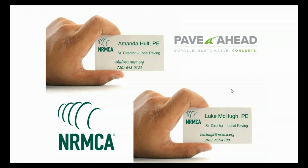So many times we might include an expansion joint in areas where we feel like there may be blowups. Sometimes when we get to toll facilities, we'll put lugs in there to keep movement of panels limited, particularly when we're using CRC pavements. So in those types of situations, sometimes we might include an expansion joint there just to accommodate a little bit of that movement, but also keep the sliding to a minimum.